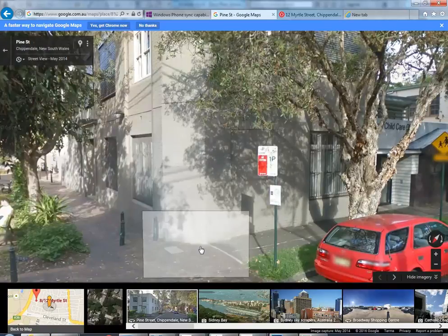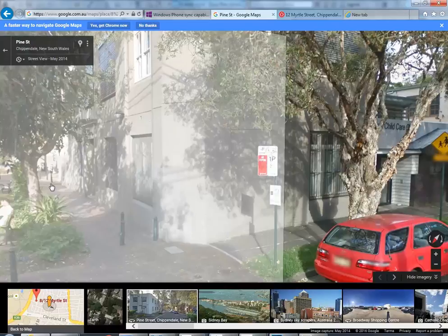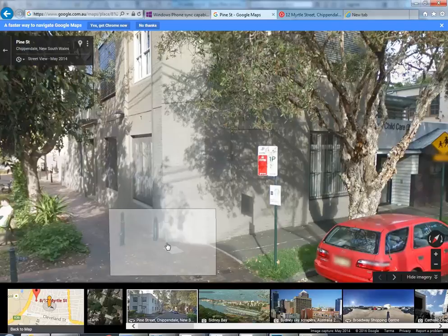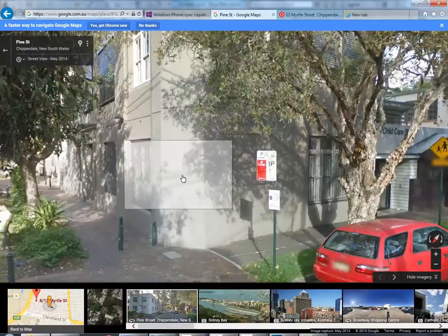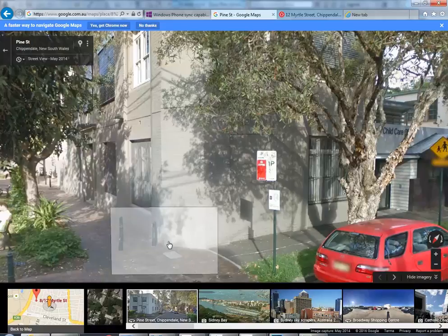I'd say there's a good chance that the brickwork is supported on its own footings. So the brick walls here could go down below the floor level, the pavement, to probably pretty pathetic footings, because that's the way things were built in the 19th century when this was probably built. So that's the way it would be in real life. You've got to be aware of that. And then the floor structure would be inside those walls.